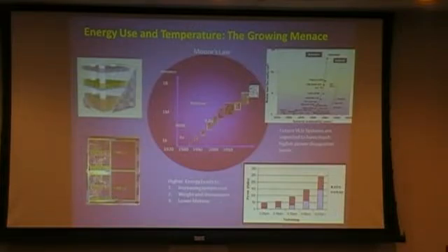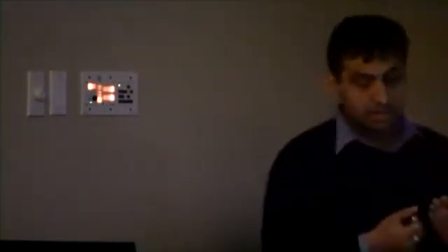And this increase in silicon densities is accompanied by a significant increase in the energy and power that these systems take to operate. As shown in this curve over here, which probably is not very clear given the density of the slide, there are two components of chip power, leakage and dynamic, or static and dynamic. Dynamic power dissipation in large-scale digital systems is caused by switching of transistors, and leakage power happens because you have a sneaky leakage current that you are always draining, even when you're on and even when you're not doing